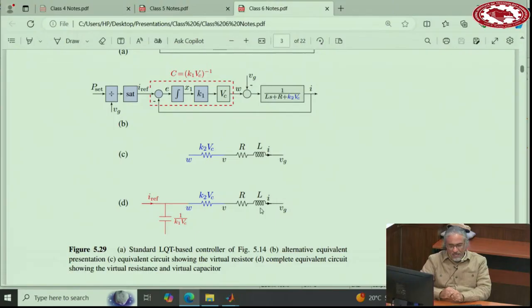And vice versa. If there is a load in this grid that disconnects, the voltage tends to go up, then the voltage across this line tends to go up. The capacitor voltage tends to go up, and the capacitor absorbs energy. So it's a stabilizing behavior. Got it? Very similar to what we got in a synchronous machine. So this control that we have here is like adding inertia. However, the problem is this one.